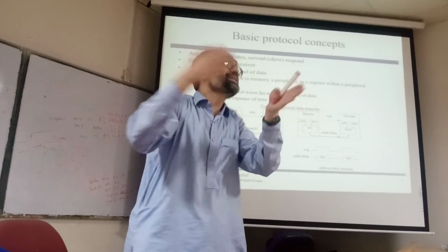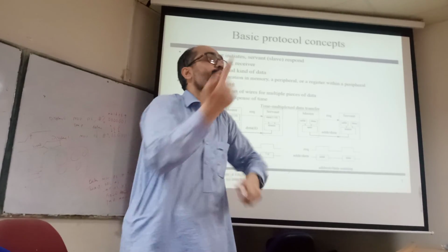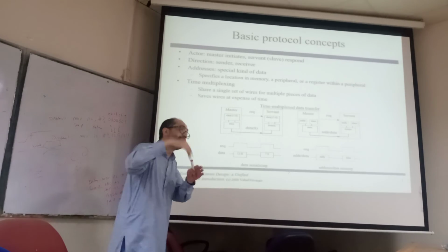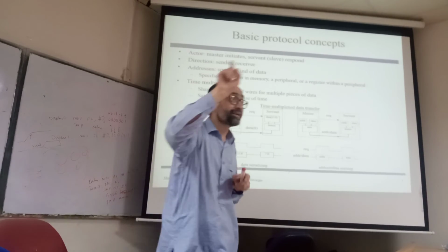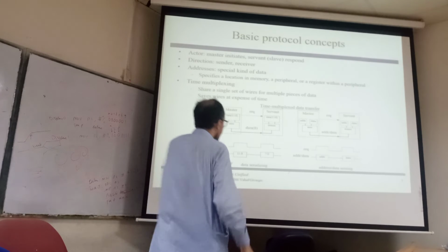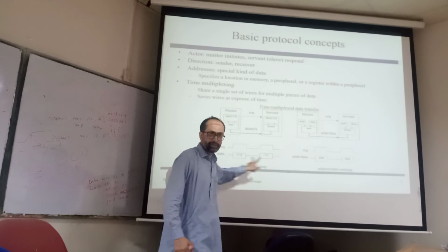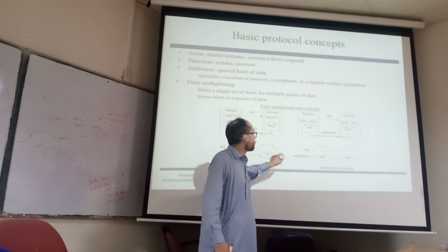If the data bus size is equal to the data size, you need one clock cycle. But in this case, you need two, not one clock cycle; it can be multiple cycles. To get the data, how many transactions do you need? Two transactions: one transaction to get the highest byte, the other to get the lowest byte.